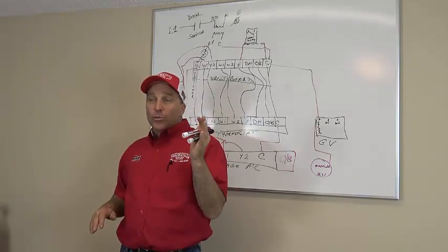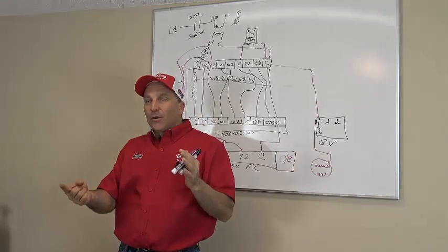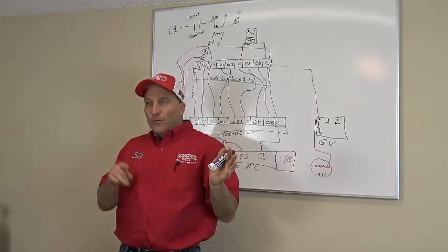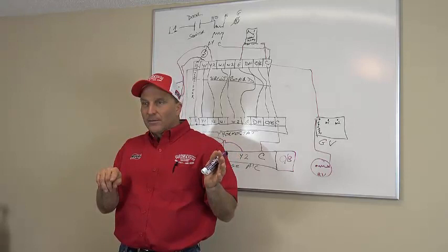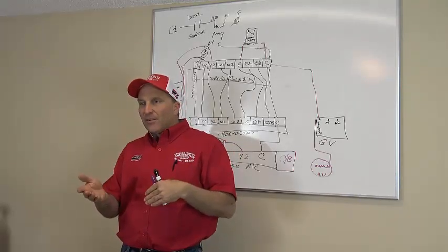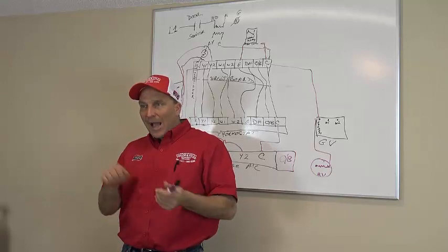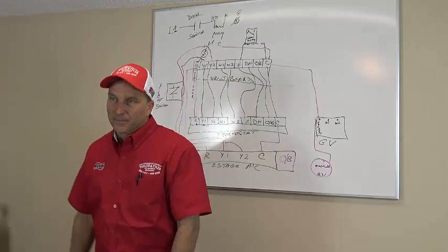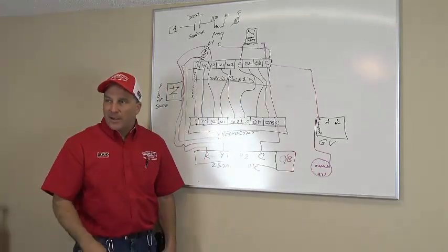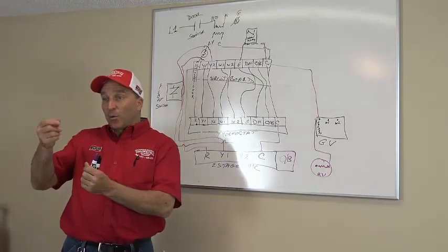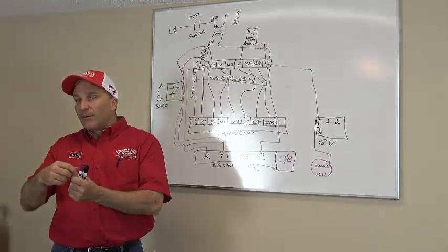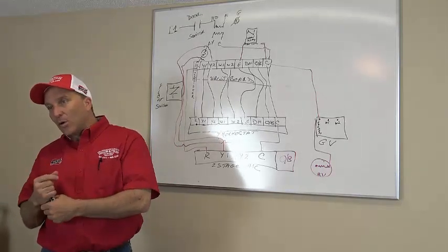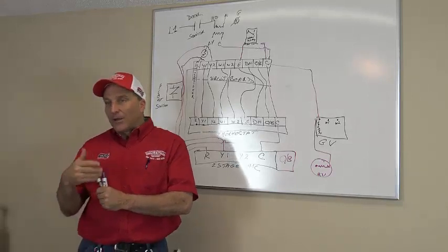Because if you have no load to it and there's power to it, you're going to read 120. Put a load to it and it disappears. Your voltage was there before, you read 120, right? Now you put a load to it, you're reading 70, it's not running. Well, you had 120, so your power is there somewhere. It's probably your common coming back. Bad wire nuts, whatever may be the case, not all connecting. Stranded wire, a lot of your strands are broke off of it and you only got two left. You'll read it, but when you put a load to it, you ain't going to read it anymore, because you don't have enough wire to bring the voltage back to it and make that load run.